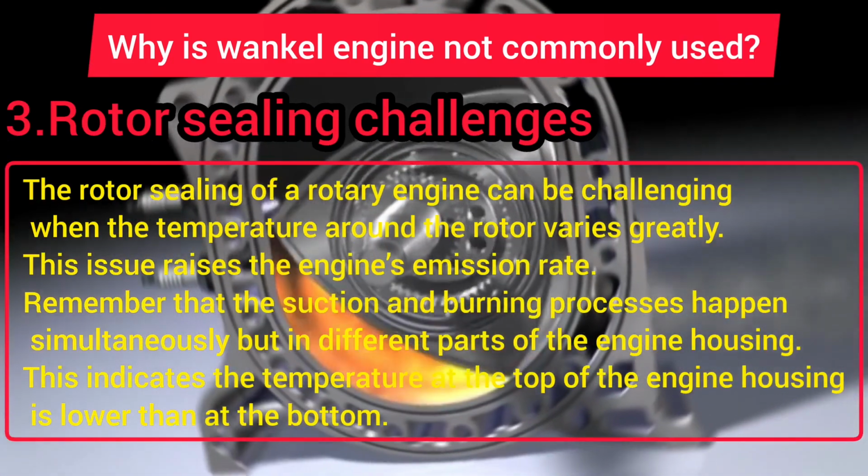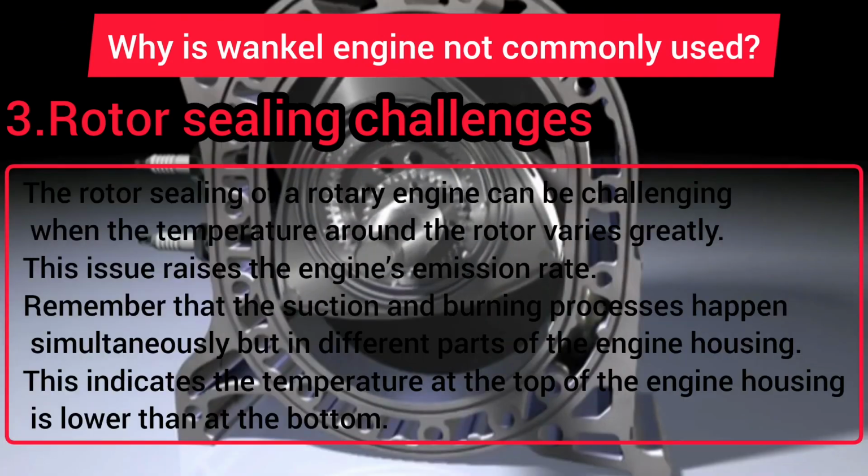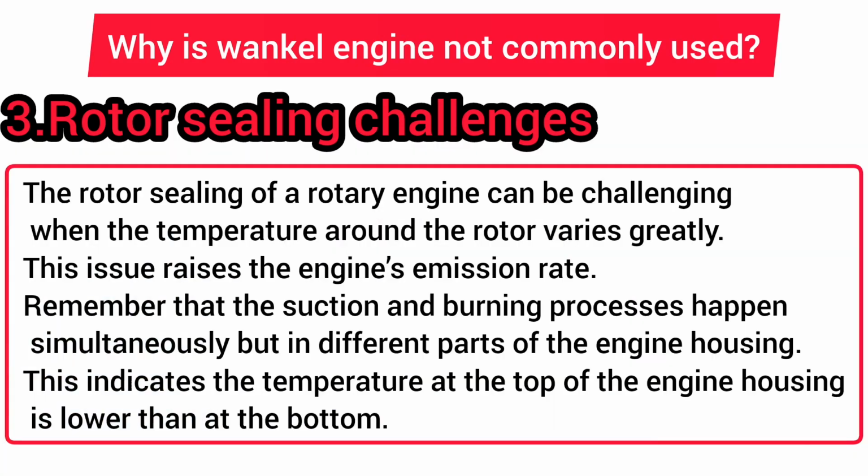3. Rotor sealing challenges. The rotor sealing of a rotary engine can be challenging when the temperature around the rotor varies greatly. This issue raises the engine's emission rate. Remember that the suction and burning processes happen simultaneously, but in different parts of the engine housing. This indicates the temperature at the top of the engine housing is lower than at the bottom.